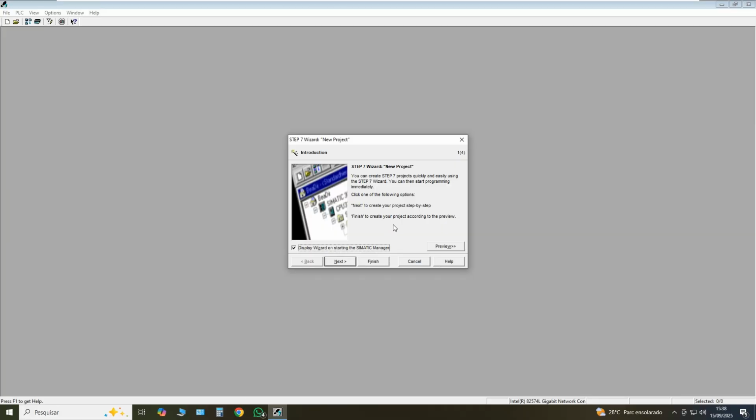Okay, so in this system, I have two temperature transmitters from Endress+Hauser, model TMT84, and they're Profibus PA. So I have to set up the bus address for them, but to set it up, I have to use an optional display, which we didn't buy.